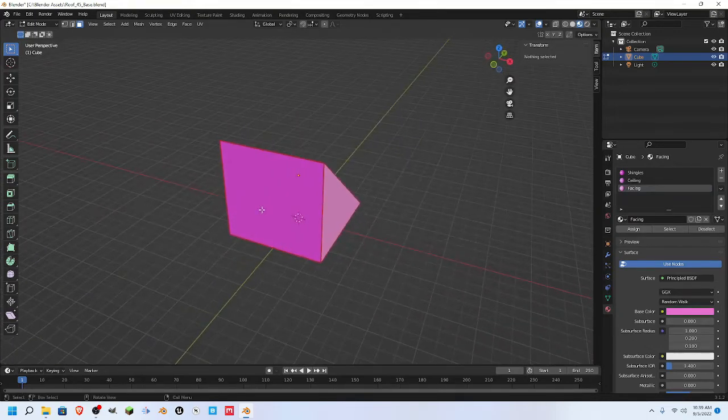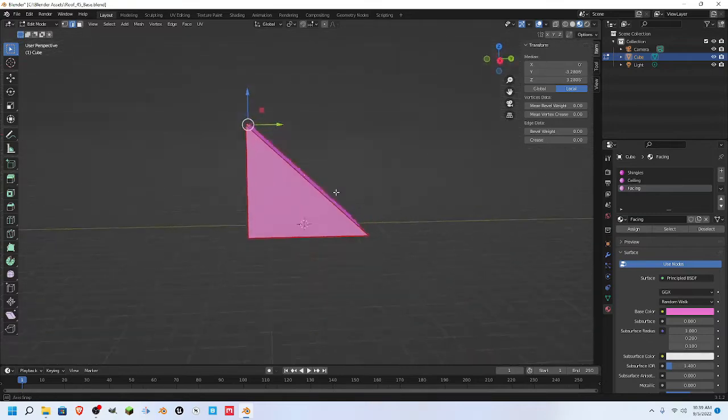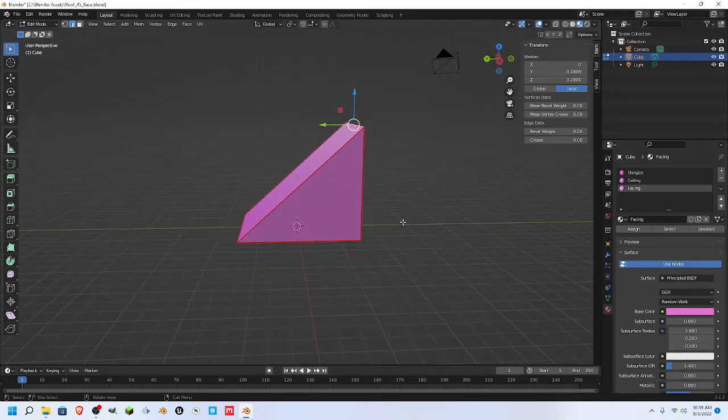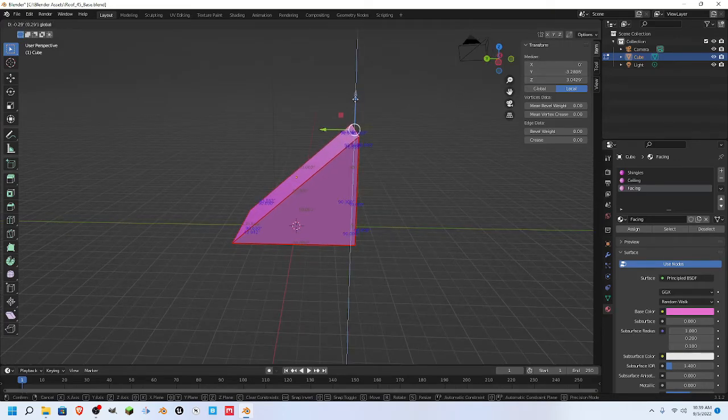Alright. Now, grab this edge right here. I'm going to need face angles. Does this have face? Yeah, it's got face angles. Alright, so we're going to bring this down to a 4/12, which means that I need to make my degrees read 20.